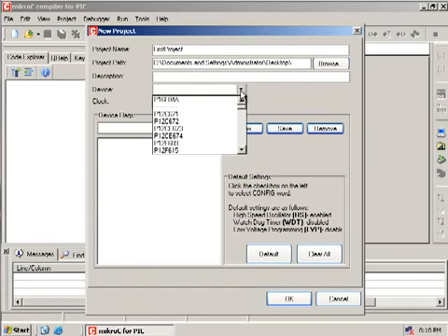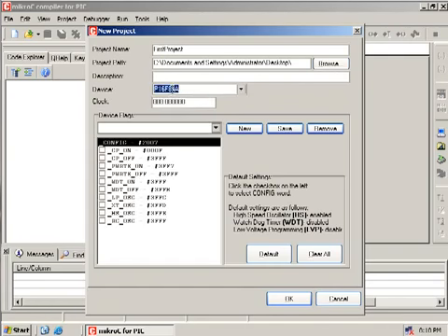And also here you have to select the device. I selected the PIC16F84A microcontroller, and here you have to specify the clock speed that you are going to use, and I selected 4. The 4 means 4 megahertz. When we are implementing our project, I will tell you what the clock speed is and why it is important. And here some configurations are available.